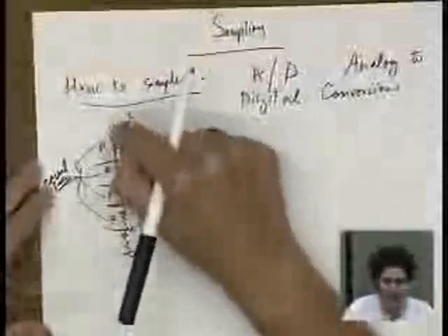And what do people do to make the resistors equal? They design it, they build it, and then they take a laser trimmer and they trim the resistors manually by hand at the end to make them all equal, in some cases. Okay, if they want extreme accuracy.